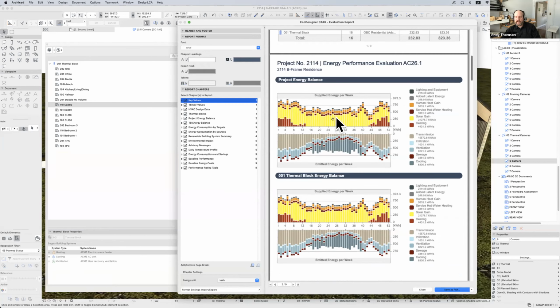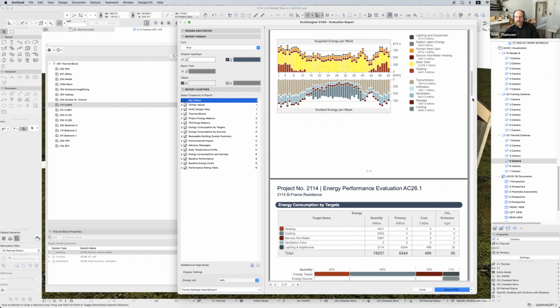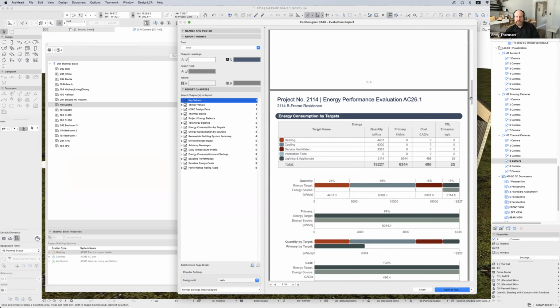Well, there's a lot of gain in that south-facing window. This is that yellow, that double line, that double happiness. I want to squash that in the middle. I've got some pretty good ventilation going right now because I've told the profile to run ventilation, dump as much of that heat as I can, but I still have to cool. And that's these little blue things here. Oh, sorry, the dark lines are cooling. I'm sorry, I haven't applied my ventilation yet. So the cooling energy is the highest load in my overall file.